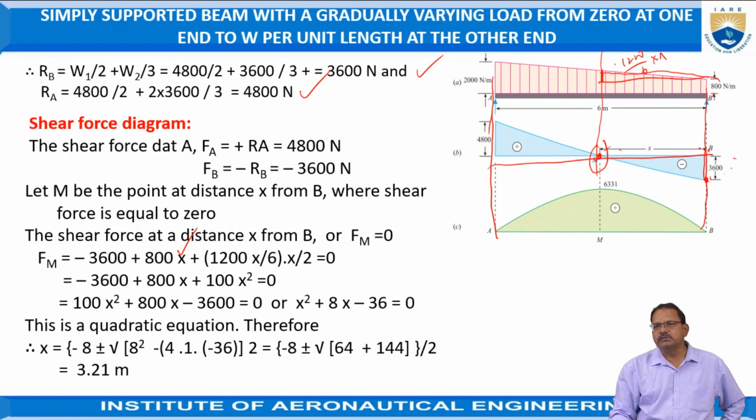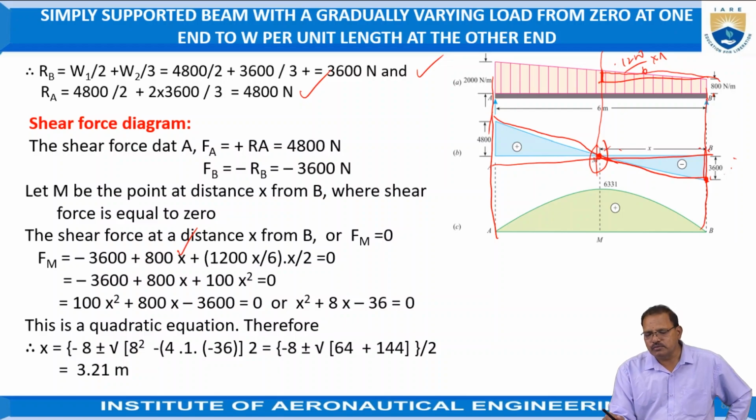So join all these points using a parabolic curve, from this point up to these positions. This is known as the shear force diagram for the beam subjected to both the uniformly distributed load as well as the gradually varying load.